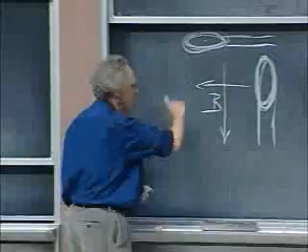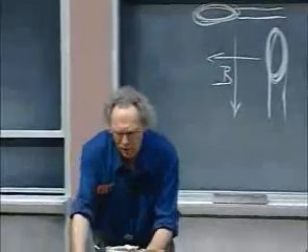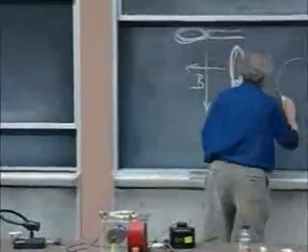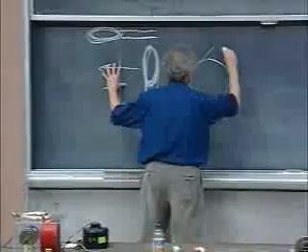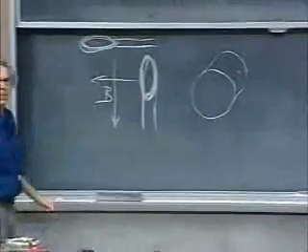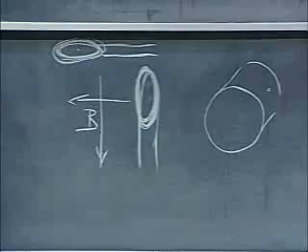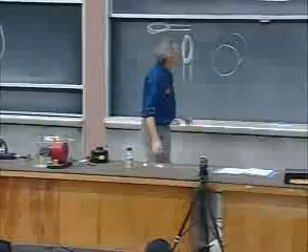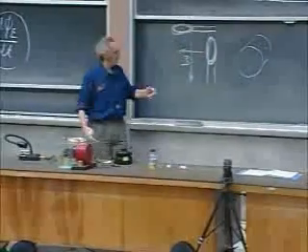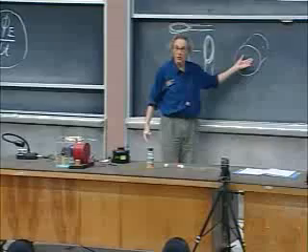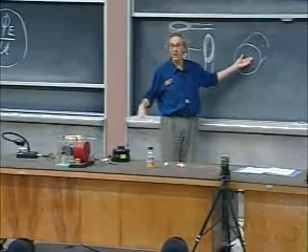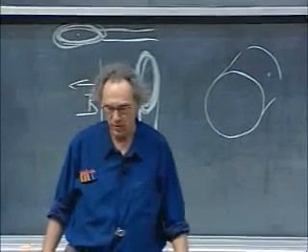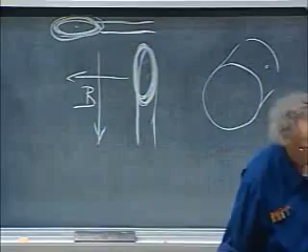And if I put in here a can, a paint can, we use a coffee can, it's right here. Then at the surface of that can, so I will draw the can here, but it's really there. At the surface of that can, you're going to have eddy currents, because you have change of magnetic flux all the time, and these eddy currents with the magnetic field will cause a torque on this can. And the torque will always be in the same direction, and the thing is going to rotate. So it's another example of an induction motor. It's a very cute one. And I want to show it to you.